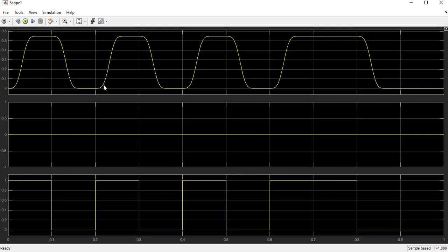Okay, so you can see we have lost a lot of components. This estimated signal is somewhat relevant to this input sequence, but there are a lot of smooth edges where we need sharp edges actually in these regions. Sharp edges means high frequency. As we are setting our f stop lower, closer to 50, we lose our high frequency components and it becomes smooth.